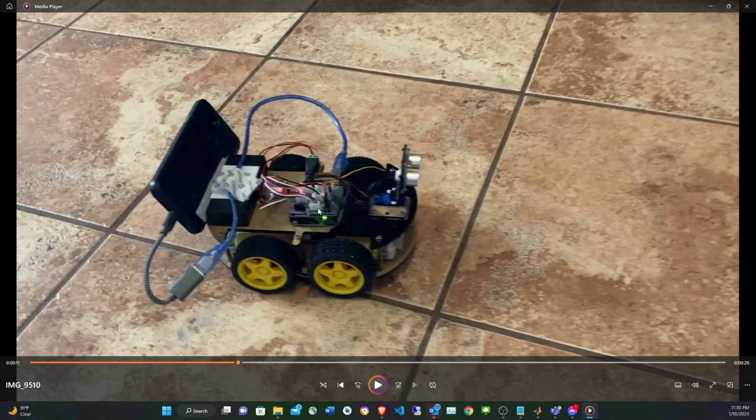Basically, we have an Arduino based Elegoo robot that has controllers for the wheels and also has an ultrasonic sensor. The ultrasonic sensor distance, which is going to give you the distance between the robot and any colliding object, is going to be sent through the serial cable to the Android phone. And the Android phone is going to tell the Arduino, through the same serial port, whether to go forward, backward, stop, left, or right. And then the Arduino is going to take those instructions and apply the corresponding controller commands for the wheels.